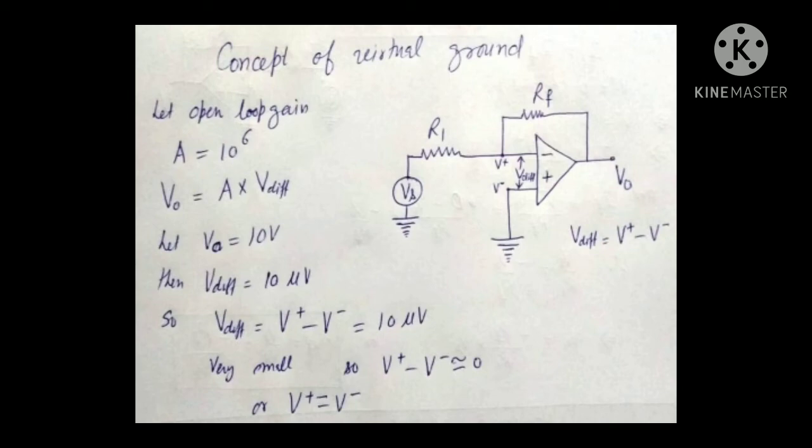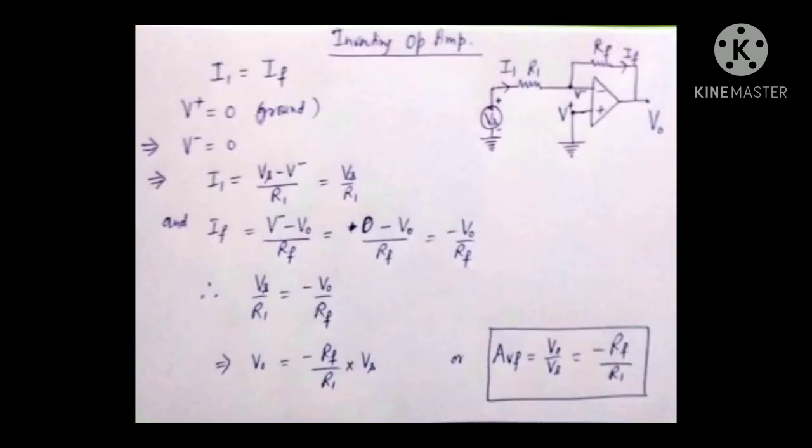These two very simple rules are the most important thing you should remember of an op-amp. So let me repeat it once more, that the first rule is both the input terminals are at same potential, and the second one is no current flows through the inputs. With these general rules in mind, let us start